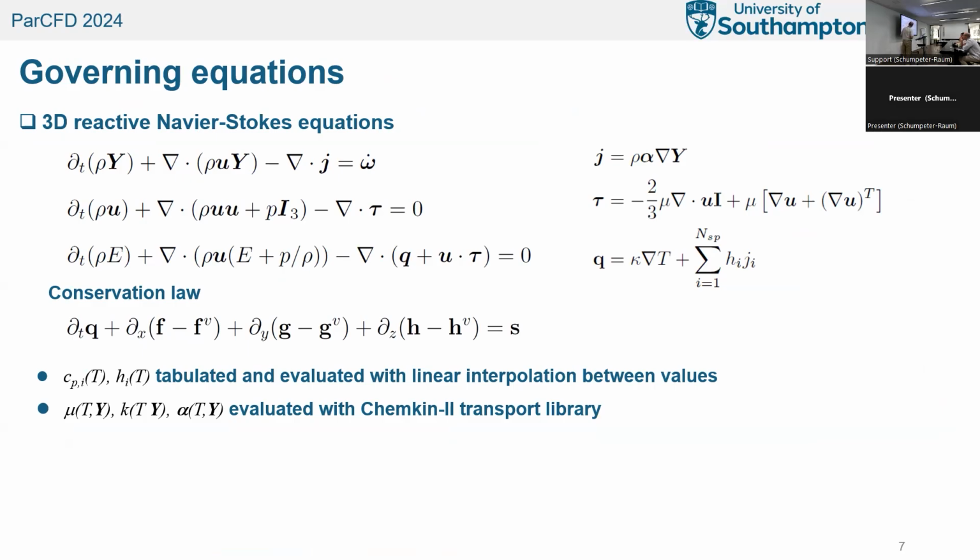The governing equations are the reactive Navier-Stokes equations that have to be solved here. As I said before, RDE combustors are non-premixed, so particularly we need the interspecies diffusion to be modeled correctly. You can only do premixed archetypical RDE, so prototypical experiments, with the Euler equation. So you really have to go to Navier-Stokes here.